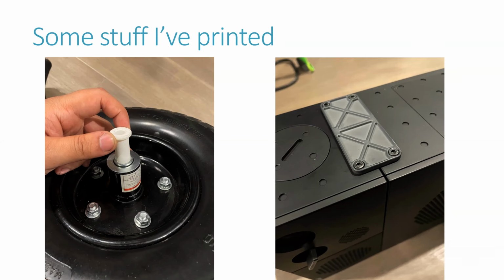I'll just jump in here really quick, Rob, and mention that I'm about to post a link into the chat for the Formlabs recommended design guide. It'll give you some recommendations on things like the maximum or minimum thickness for a wall that the printer is able to print, or an overhang, or any of those features. I think that's another great aspect of the tolerance question: what can the printer handle versus what you're trying to achieve. As long as those two things mesh, you should be fine. Yeah, great point there, Dan.